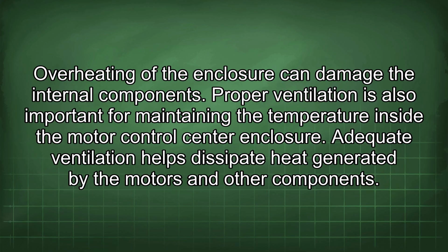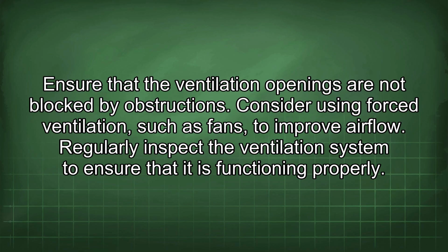Proper ventilation is also important for maintaining the temperature inside the motor control center enclosure. Adequate ventilation helps dissipate heat generated by the motors and other components. Ensure that the ventilation openings are not blocked by obstructions. Consider using forced ventilation, such as fans, to improve airflow. Regularly inspect the ventilation system to ensure that it is functioning properly.